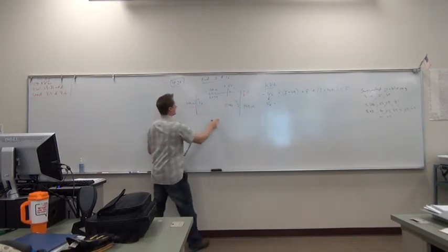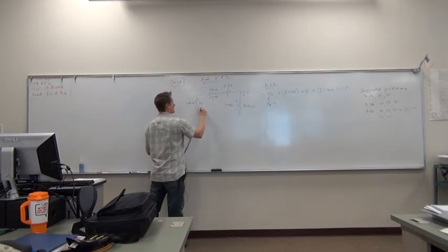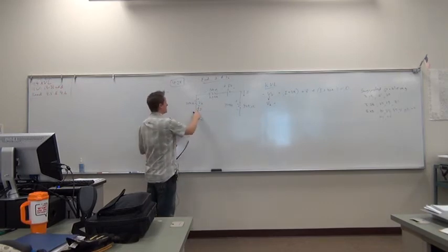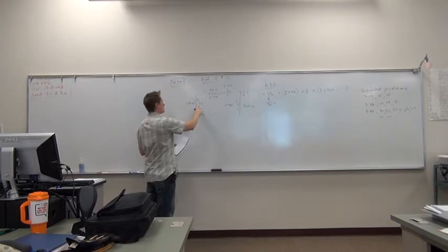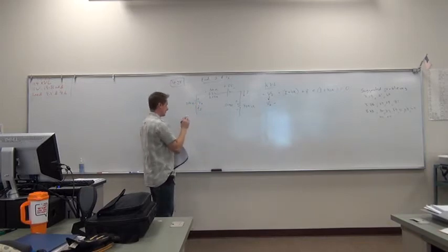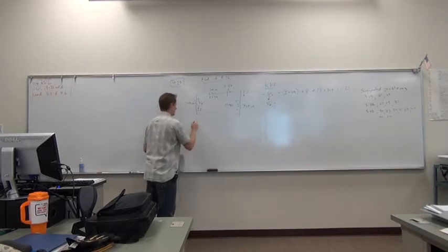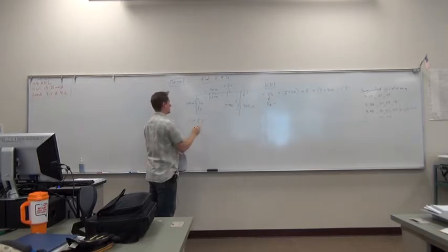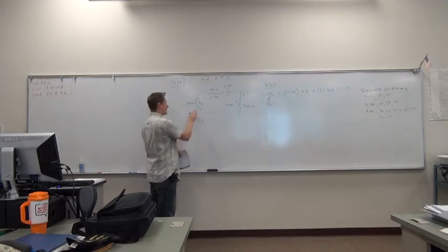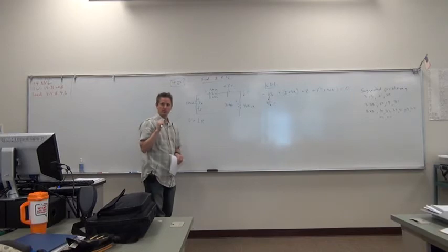This says I is coming through here and that I is going up through here. So I'm calling this I. And what does Ohm's law say? Ohm's law says that in a resistor, the magnitude of the voltage drop is I times R, and that the sign of the voltage is always in a direction that tends to cause a voltage drop across the resistor as the current passes through it.